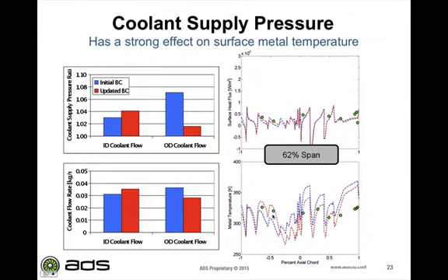but this is looking a little bit more credible on the pressure side. When we move to the suction side, now we see that large over prediction that we had been seeing once we just added on the Kapton layer. Now that's been brought down to a more reasonable level. And again, the reason for this is because we've seen an increase of coolant flow from the ID cavity, which is feeding the film cooling holes that are driving this area over here. And we've seen a decrease of cooling flow that's driving the cooling flows that are affecting this area.